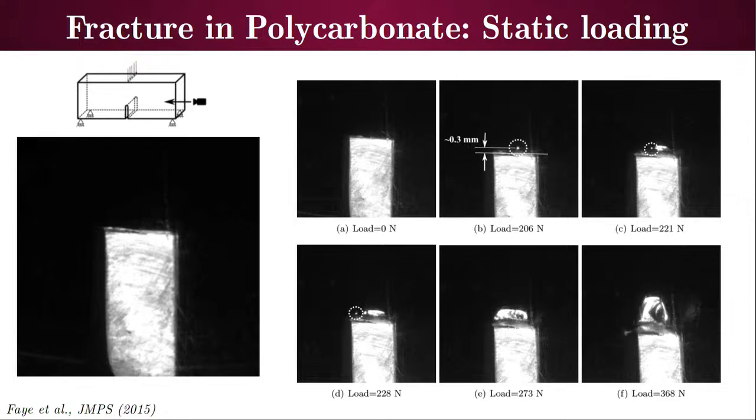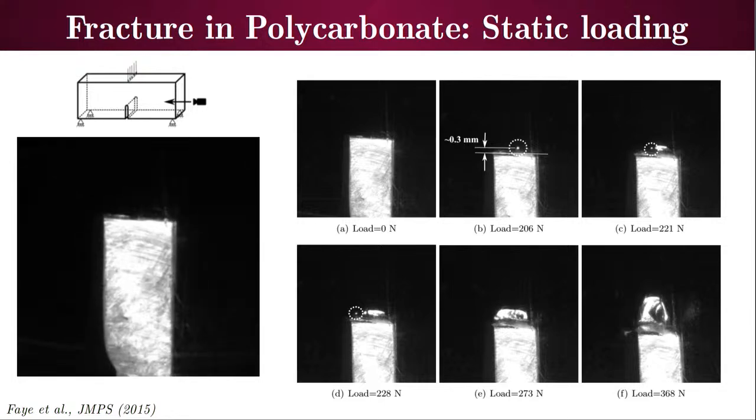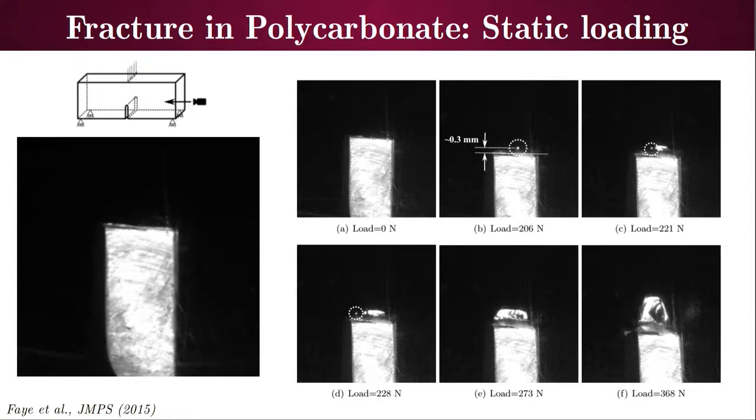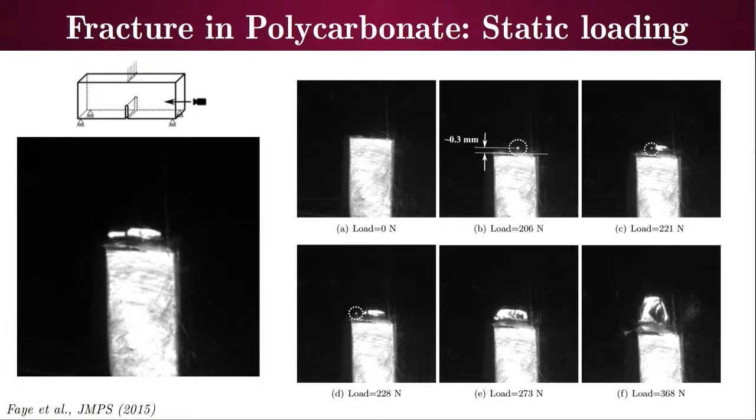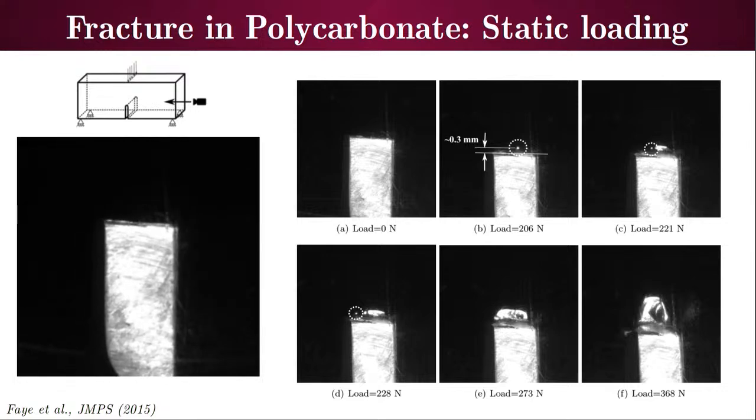Okay. So this is a static image of the same thing. Initially you can see the crack front, which has no defect ahead of it. At some particular load, a small defect appears at an isolated place. Once the load increases, this defect starts growing, and another defect appears at some other location, again isolated from the crack as well as from the initial defect.